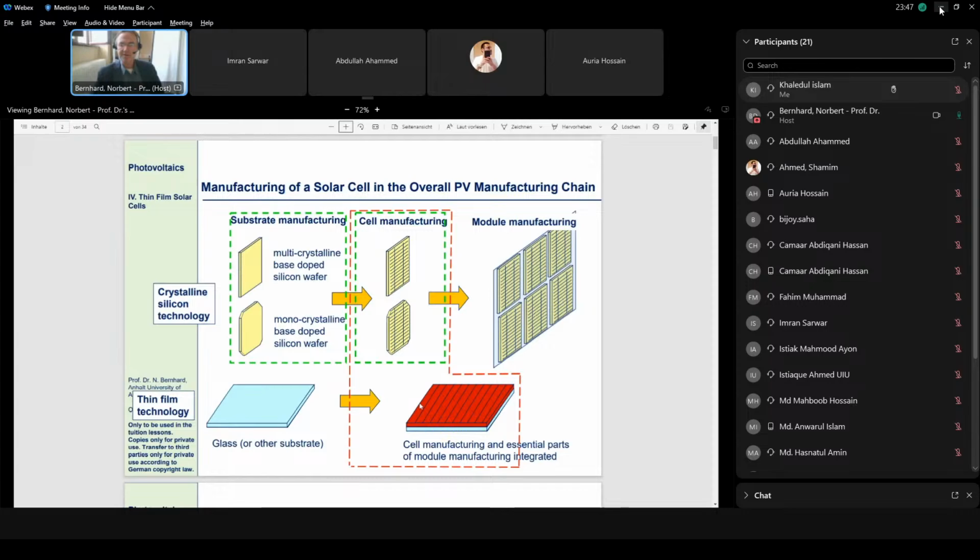Then we have the deposition of the semiconductor material. In case of amorphous silicon, it's first the doped material, usually first boron-doped, that means p-doped, from silane and diborane. Then you have the intrinsic layer only from a silane plasma, and then the phosphorus-doped or n-doped layer from a silane and phosphine plasma. This means the deposition process is plasma enhanced chemical vapor deposition.